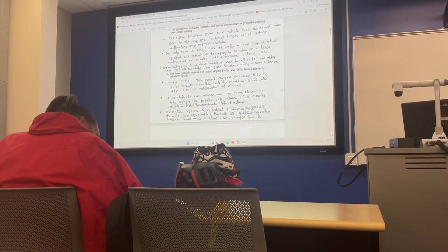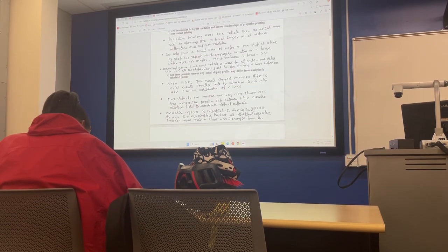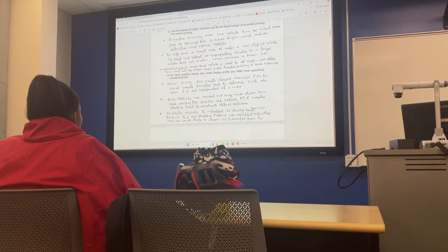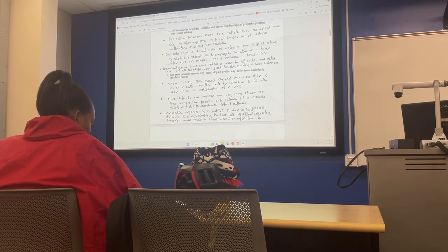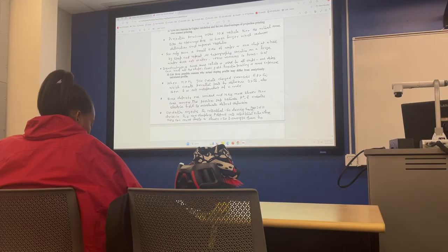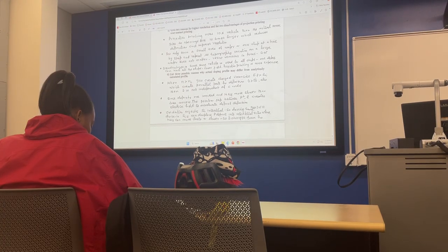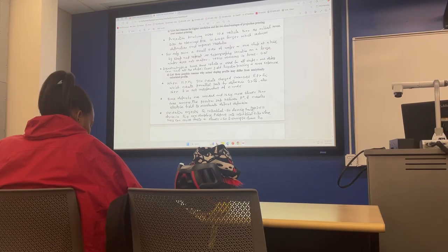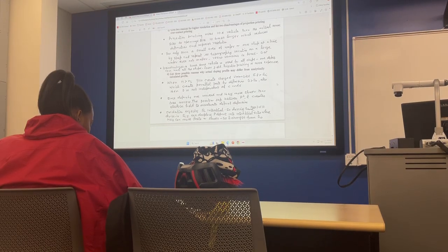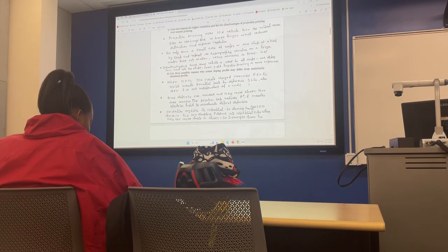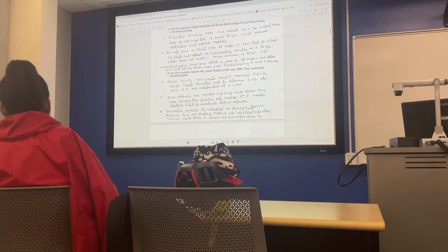The main thing is that when doping is greater than Ni, in addition to the intrinsic vacancies, you start creating vacancies that are charged. So now you've got total vacancies much greater, neutral vacancies and charged ones, and they both assist in diffusion.